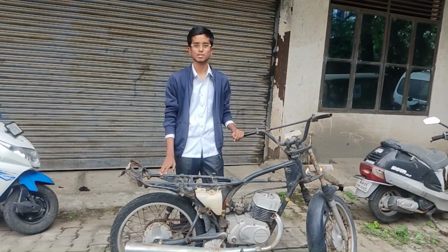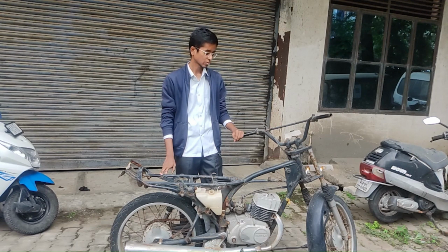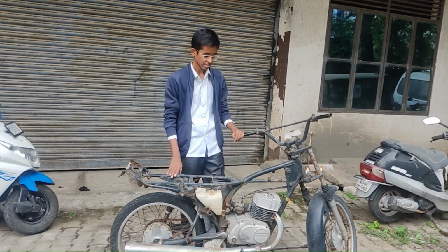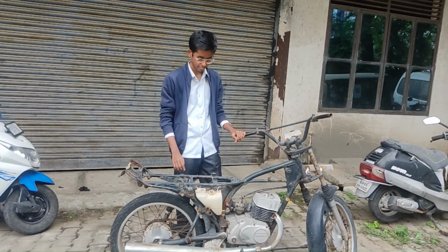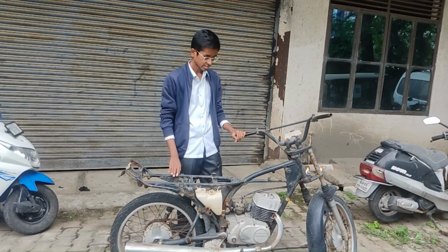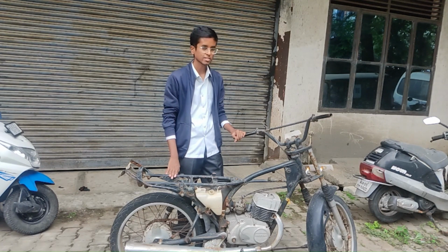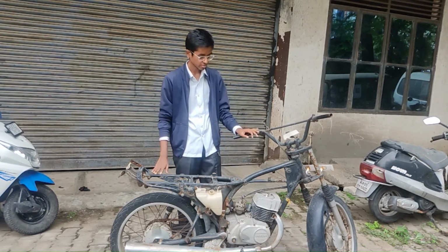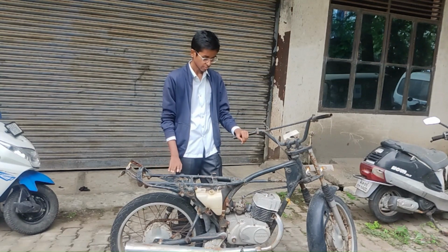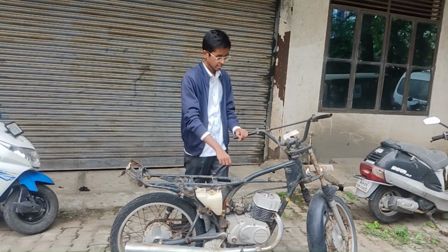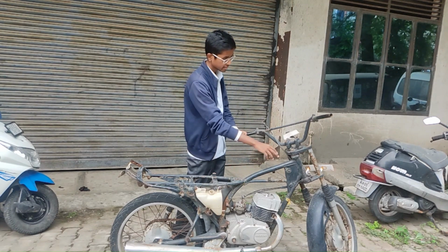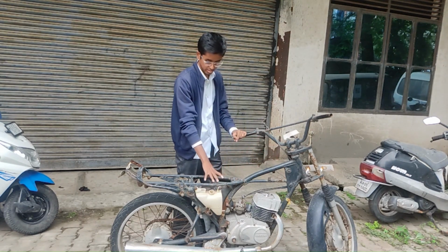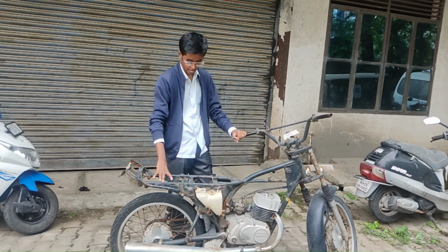Hello everyone, myself Ganesh from 6M Automobile. Today we are taking an indigenous chassis by TVS. It's an old one, a single cradle frame, used in all low-end bikes. This frame uses high-strength steel as the material, and it is a monoblock tube creating a solid structure for the engine member and connected to the handlebar, and then splits up into the cradle which supports the auxiliary brake system.